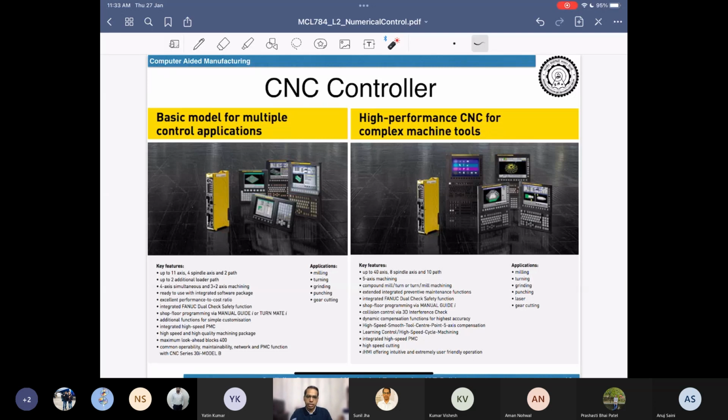For example, certain controllers are designed for milling functionalities, so whatever compensation is required and whatever geometries are to be created for milling are specially designed for those applications. These are the variations you will come across among different manufacturers. They are trying to add more value to their controller by providing additional functionalities. The basic part programming, NC control, and access control will always be the same in all the controllers.